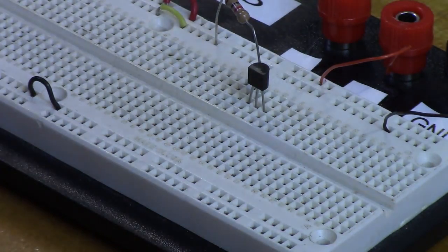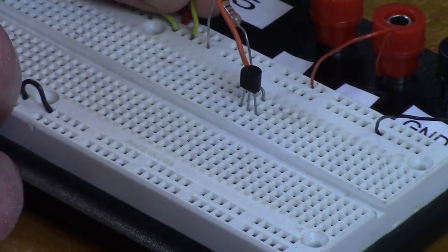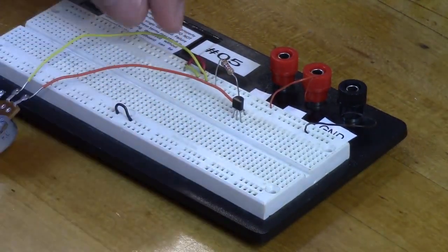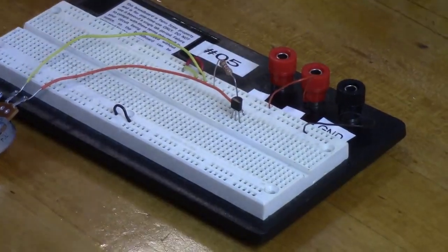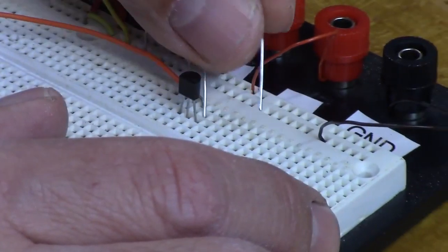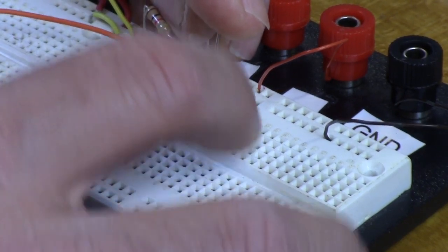We're going to have our R2, which is this 50K potentiometer. And this one, luckily, only has one lead broken off, which is actually good for us because we only need two leads anyway. I'm going to center the pot before I plug it in. And that's going to go from base to ground. We're going to set this pot once at the very beginning, and then we're not going to touch it again for the rest of the period. Okay. And then from the base going high, we have a 100K resistor that's brown, black, yellow. This guy right here. So from base to VDD, VCC, we're going to plug that in there.